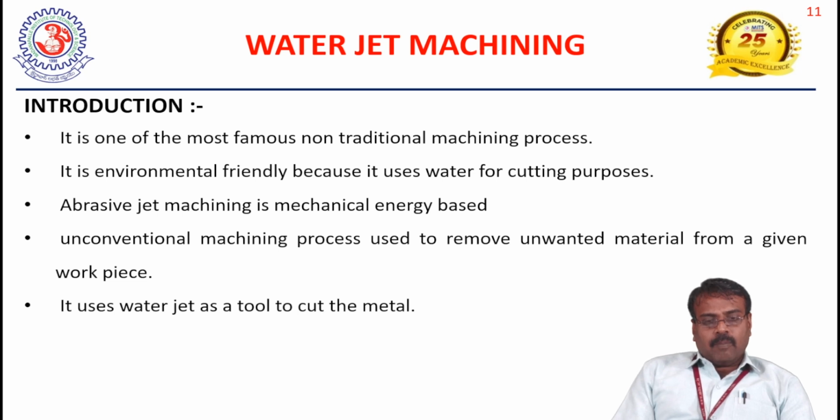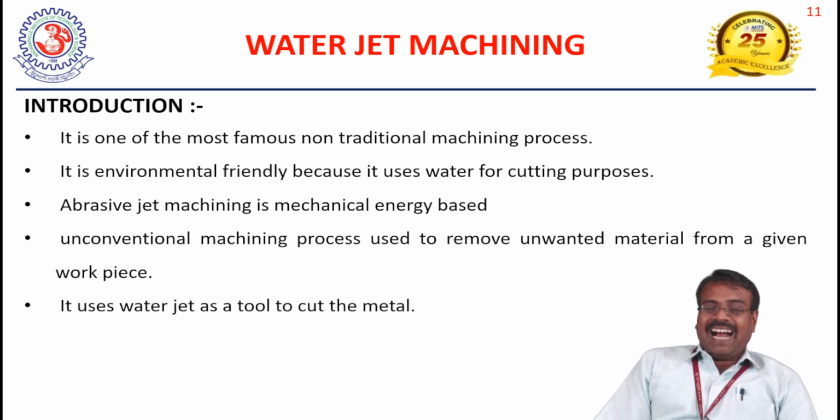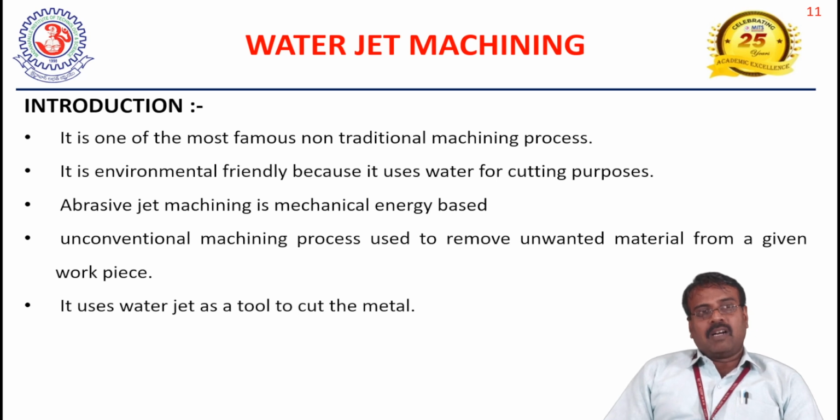Now I can compare water jet with ultrasonic or laser beam. Whenever we go for ultrasonic or laser, the laser will affect the person who is operating that machine. Those types of accidents will not happen in water jet machining. But handling is very important, because with high pressure water, if he does not take care in his process, it will affect his health also. Some unexpected accidents will also happen.